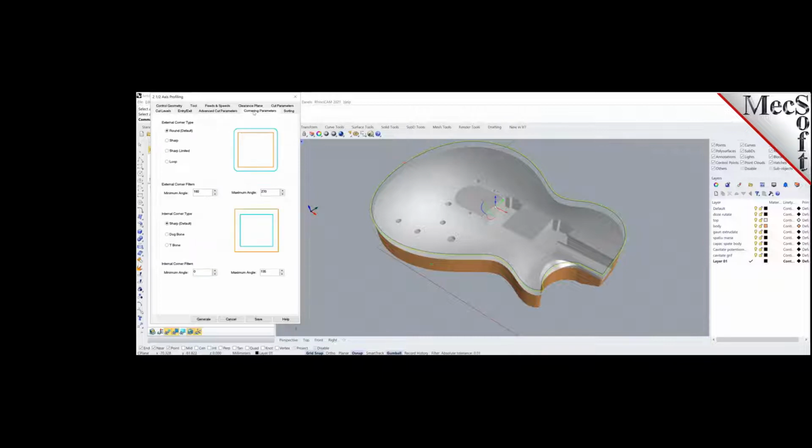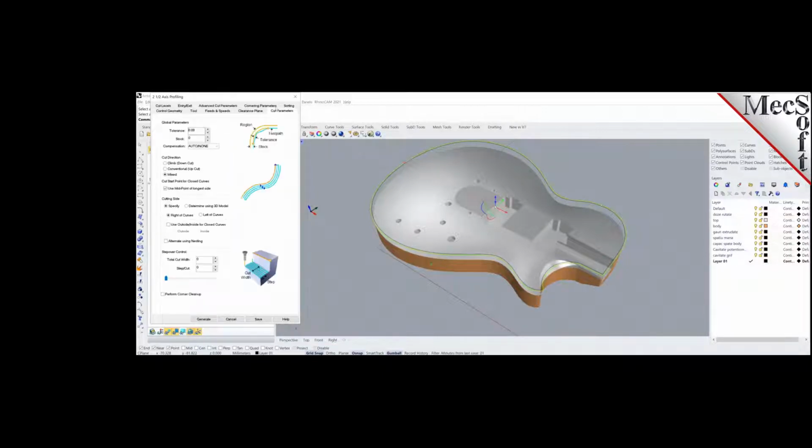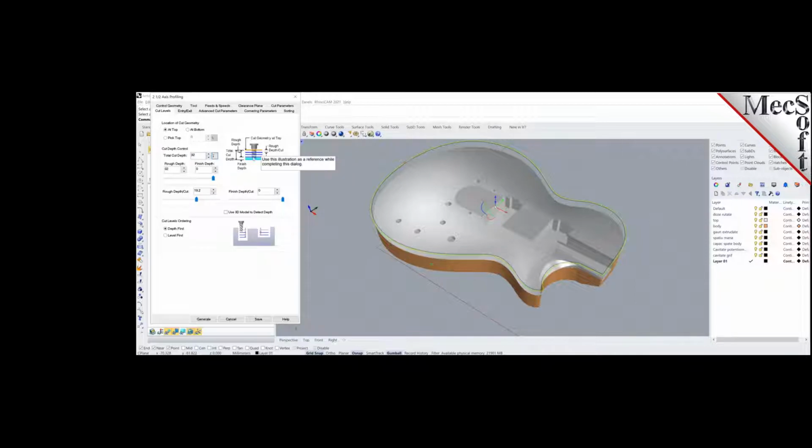I assume that I can go in and assign those manually throughout the depth of cuts. Yeah, you can set up roughing cuts if you want. You can segment the cuts into roughing and then finishing, and there's quite a bit of control for you. So you can do maybe 75% of the top section as roughing with a different cut distribution, Z distribution rather. Let's say 10 millimeters for the top 25 millimeters, and then the bottom 5 millimeters you want to do 1 millimeter cuts. You can set it up that way as well.